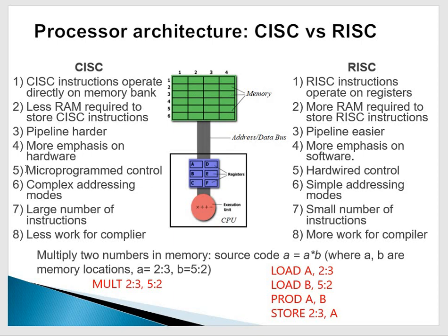As we have already discussed, to perform any operation by the CPU from or to the external memory or I/O, some control signals will always be transferred. Some control signals will always be sent to the memory or I/O to perform any operation. So the microprogram control is a type of control unit or a type of architecture in which the control signals are generated by a set of instructions, by writing small programs, the microprograms.